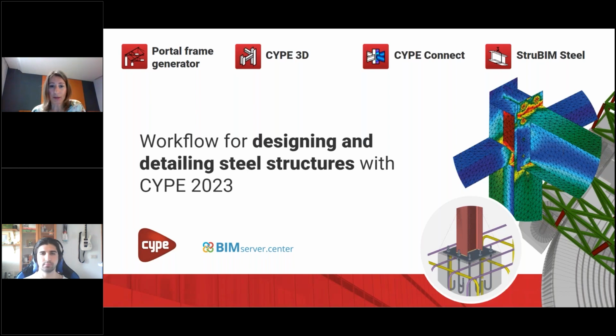First of all, my colleague David is going to show you Portal Frame Generator, where he is going to create a portal and then send it to CYPE 3D to finish the project and analyze it. And then from there, he's going to send it to BIMsteel and CYPE Connect to do the detailing and the steel connections. He's going to design and analyze the connections, as well as extracting the sub-drawings.